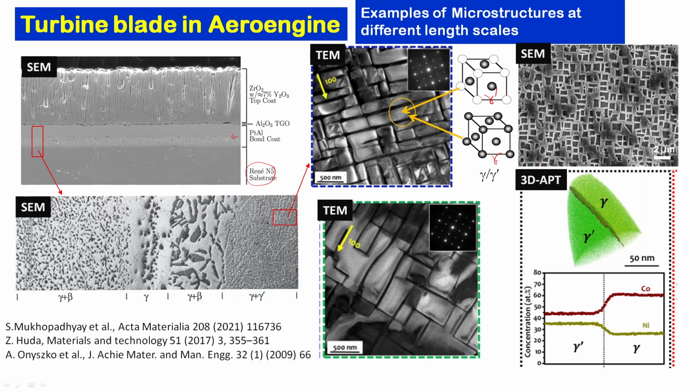So you have the base material and then you have the top coat. Top coat is normally an insulating material like zirconium dioxide with a certain amount of yttrium oxide, that is because we have to stabilize the phase of zirconium dioxide. Zirconium dioxide has different kinds of phases, monoclinic, orthorhombic, cubic. So we have to stabilize the cubic phase, that is why 7% yttrium oxide is added, and this is directionally grown crystals of zirconium dioxide so that it can provide you maximum thermal resistance.